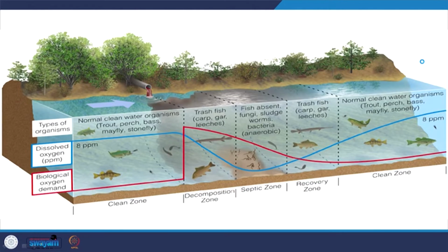So, here we have an example, we will just take a holistic view and move on. Here I have my stream coming in, so upstream of that my dissolved oxygen is pretty good and the BOD, or the organic content, is very low. Thus the aquatic ecosystem is thriving, let us say. But right at the point of mixing, BOD is very high in my particular wastewater.